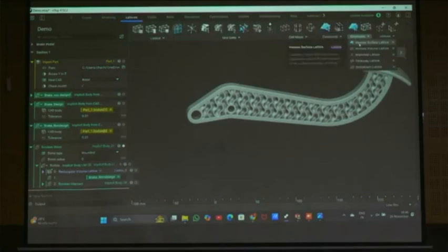There is a Voronoi surface. On the surface also we can, like whenever we say texture, that will be applied to the surface only. The term we are using, texture, means that will be applied to the surface bodies only. That is not applied to the 3D body. Okay. Surface lattice means we can apply the texture. Volume lattice means entire body we can apply. Voronoi we call it as. Voronoi means random points it will apply, there is no uniformity actually. That we call it as a Voronoi.